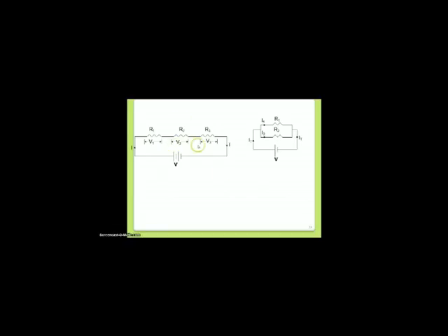So let's have a comparison between series network and parallel network. Okay, starting with the series network. So the information about the current is that there is only a single current flowing through the entire part of the circuit, but the voltages can be different. And these voltages are derived from the supply voltage, or we say that the supply voltage gets divided into individual or separate voltage drops. So in a series network, voltage divides.